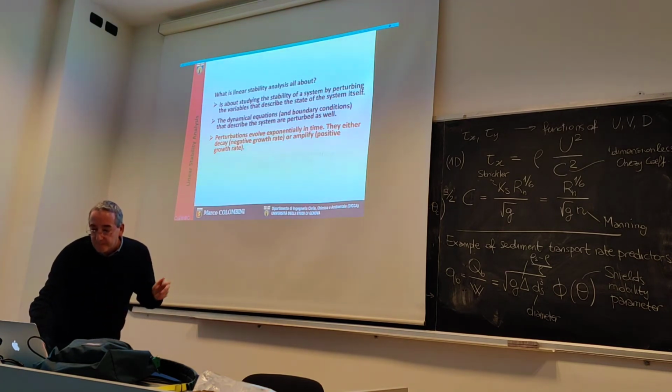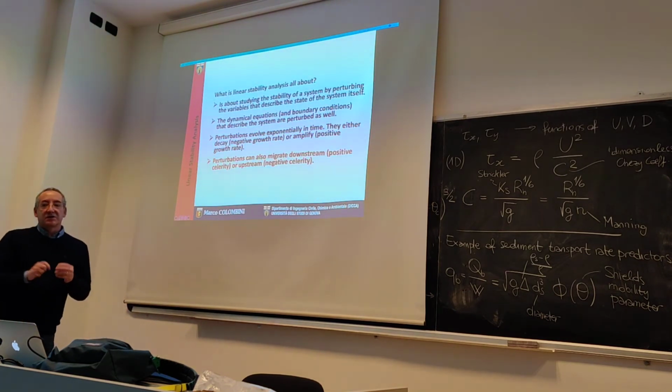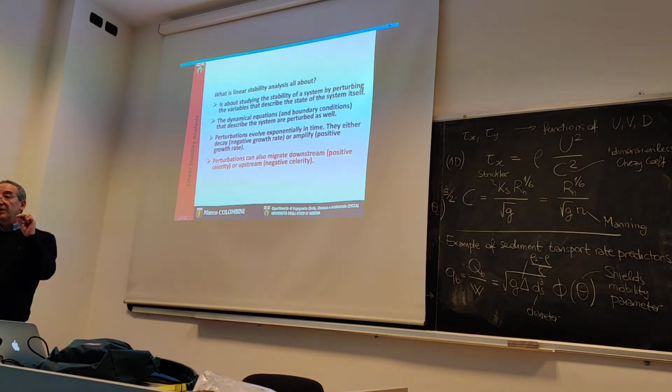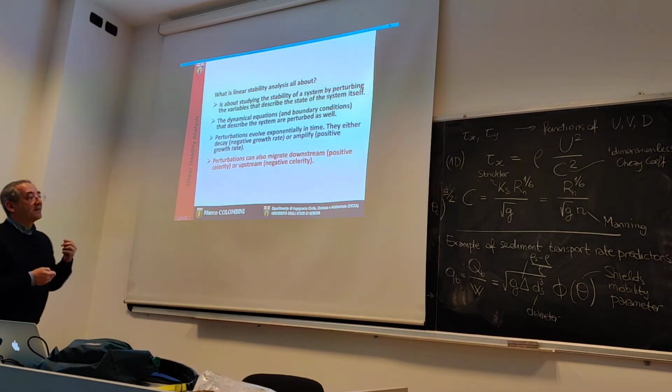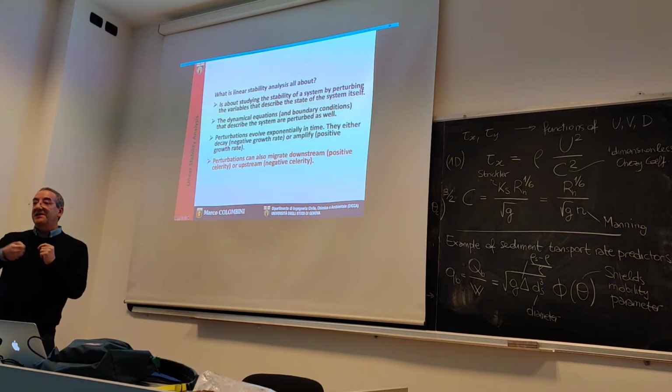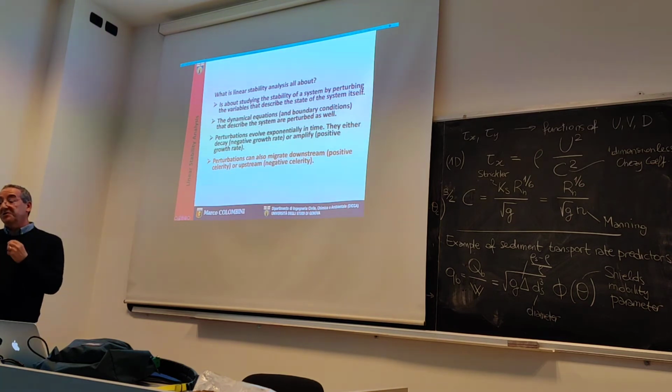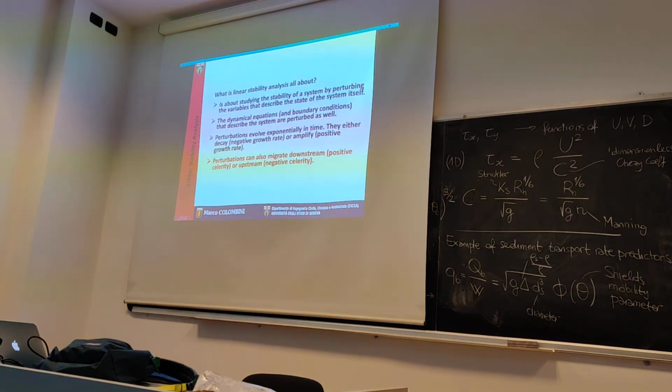Back to the characteristics: we have no information on the amplitude, but we have information on the growth rate. We will discover that if the growth rate is positive, the system is amplified, is unstable. If the growth rate is negative, it will decay. But we also have information on the celerity, on the wave speed of the bedforms, which is again an important piece of information that you obtain from linear stability analysis.